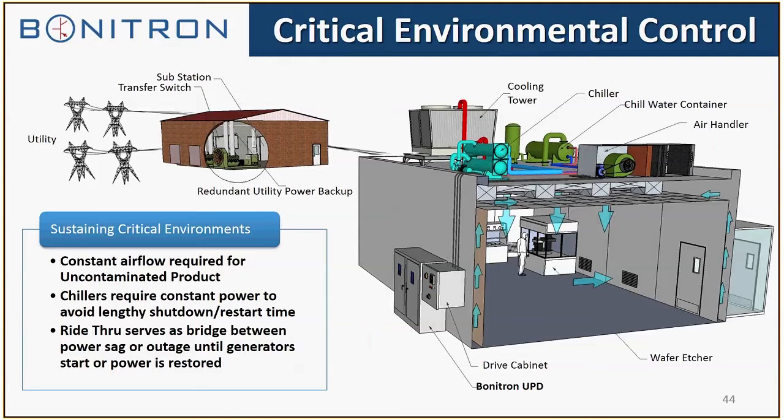So that's why at the process level, the drives are backed up. At the distribution point, the drives are backed up. And a lot of times you'll find a gen set that backs it up too to make the system completely bulletproof.